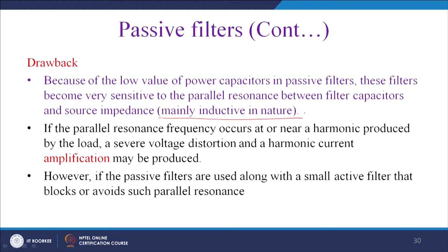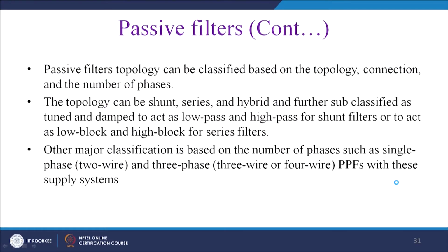If the parallel resonance frequency occurs at or near a harmonic produced by the load, severe voltage distortion and harmonic current amplification may be produced. So, this is quite dangerous. However, if passive filters are used along with a small active filter, it blocks or avoids the parallel resonance. So, this is something we have to keep in mind.